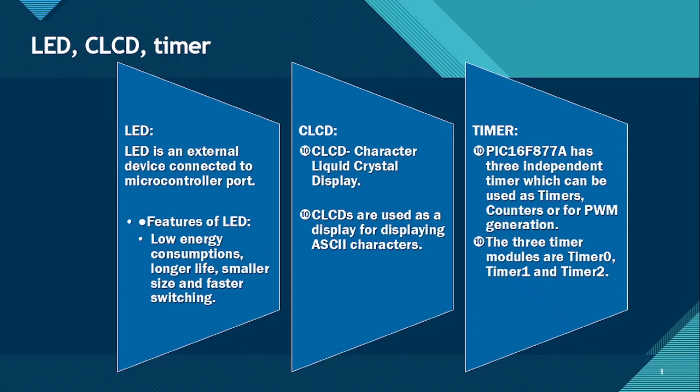Moving on to Timer 2. Timer 2 is quite different from the other two timers. It is also an 8-bit timer. It has a software programmable prescaler, while it also has a postscaler. It is readable and writable in nature.